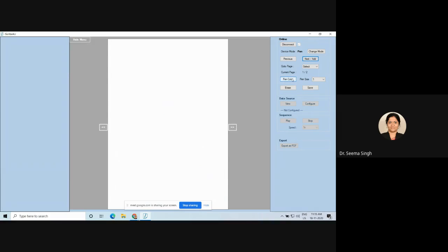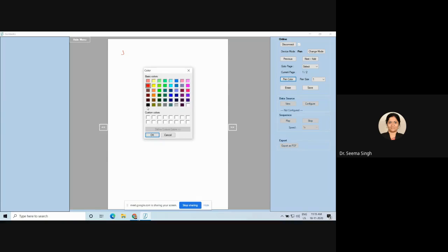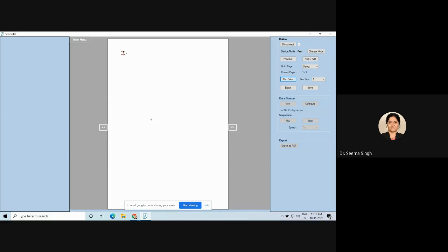Now the next step is I need to write the equation for these 6 excitation inputs. So the equations will be J1, K1, J2, K2, J3, K3. These are my excitation inputs, and this is a function of what? Can somebody tell me? What makes the change in J1, J2, J3, K1, K2, K3? It is always your present state. And what is the present state now? Present state is Q1, Q2, Q3. So now you are supposed to make 6 K-maps, and they will be made based on the excitation table which you have made just now.